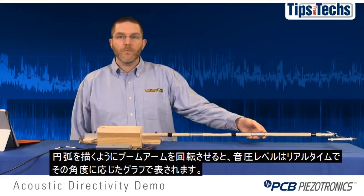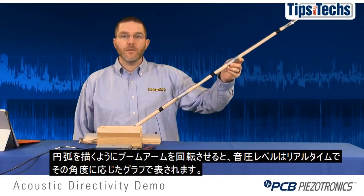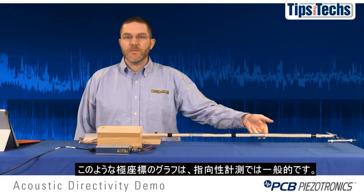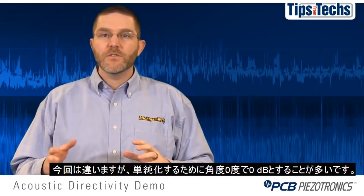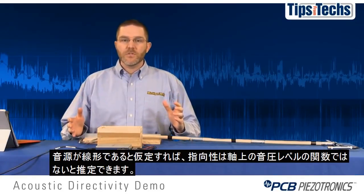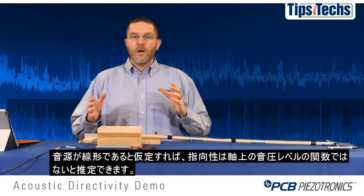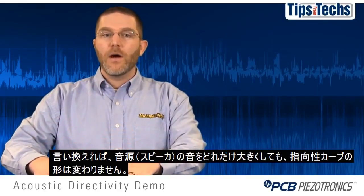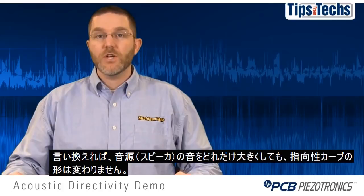As I move the boom arm around the arc, the sound pressure level will plot as a function of angle in real time. This type of polar plot is common in directivity measurements, and although you won't see it here, it's oftentimes normalized to 0 dB at 0 degrees for simplicity. We're assuming the source is linear, so we can infer that the directivity is not a function of on-axis sound pressure level. In other words, no matter how loud I play the source, the speaker in this case, the shape of the directivity curve won't change.